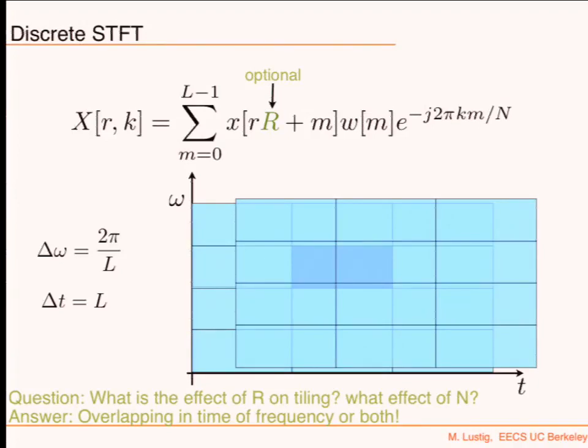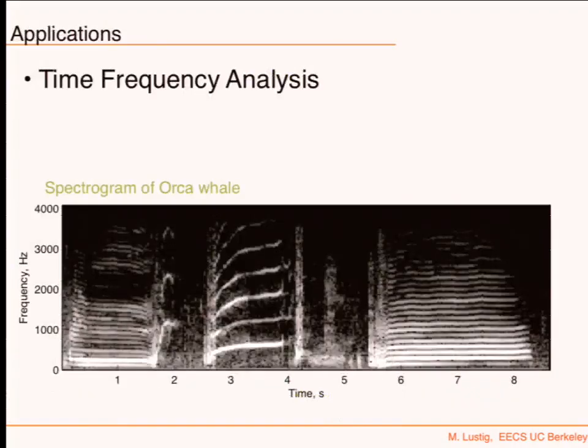Okay? All right. So then I had this example, like a spectrogram of an orca. You look at the dynamics of different frequencies that happen at different times, and the choices that you make will enable or not enable you to distinguish between those frequencies and those rapid changes. Okay, if something changes rapidly in time and it has very high resolution frequencies, there's no way that you would be able to resolve it. There's going to be a certain uncertainty that you'll be able to resolve or not.